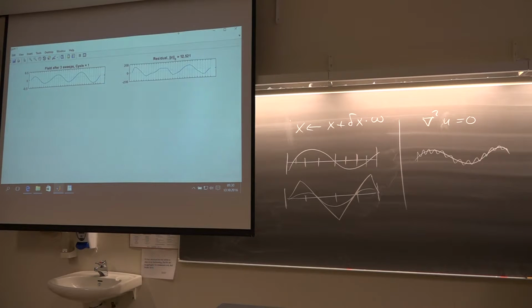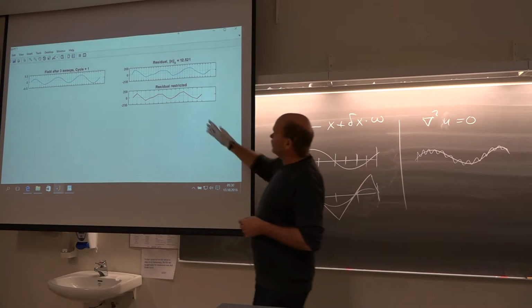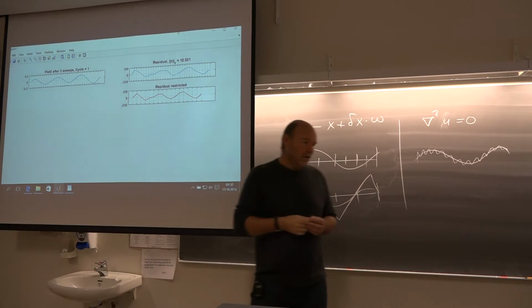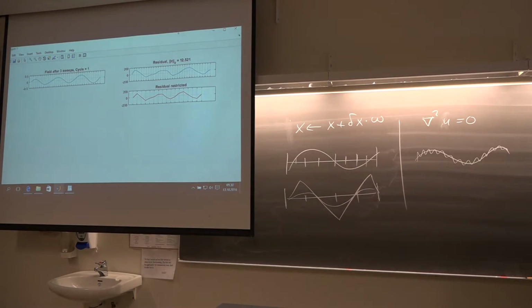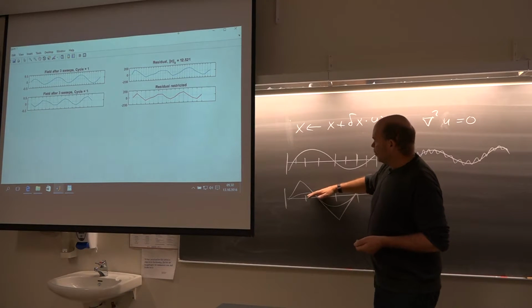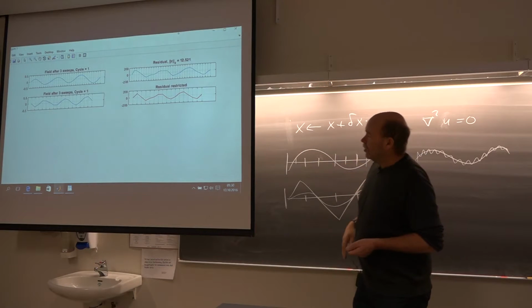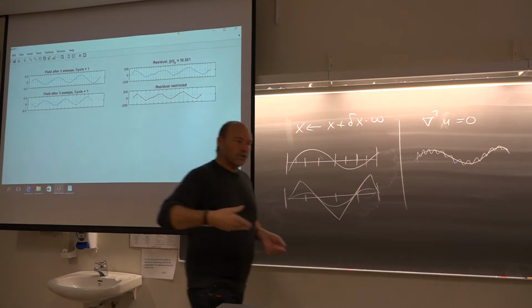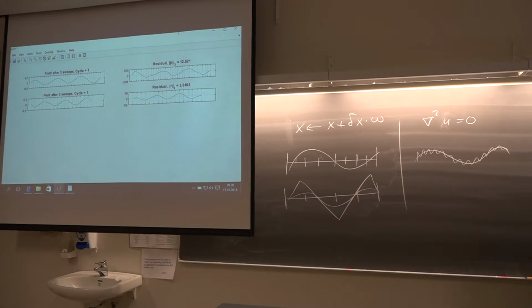So what we do, we calculate what is called a residual. Then we transfer this residual to a coarser mesh. So here is only half the amount of points. And then we solve the equation system down on this coarse mesh, and we do a couple of iterations there as well. Now, instead of jumping back to the fine mesh, I want to solve it here as well. And then I just continue to coarser and coarser meshes, like this.